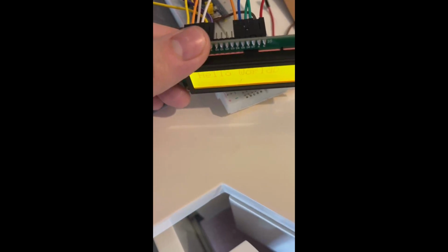If your wiring is not correct and you plug in an ST link or some kind of power source, the LCD will not light up at all. If it is correct, even if you don't boot any code, the LCD should light up. So that's just something to look out for. And yeah, as you can see, there we have it.